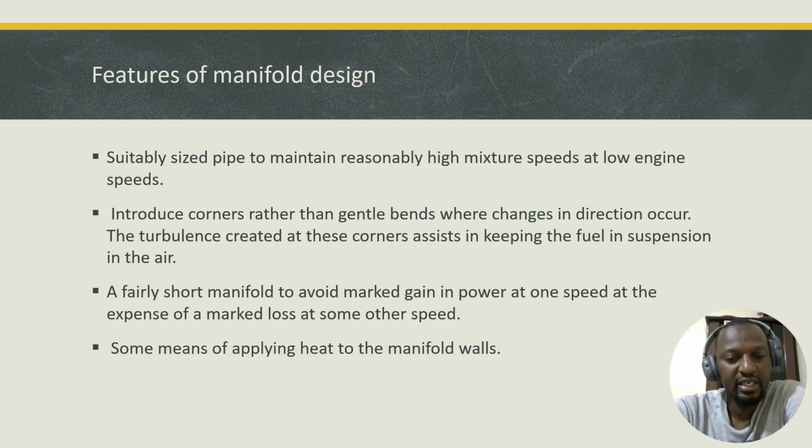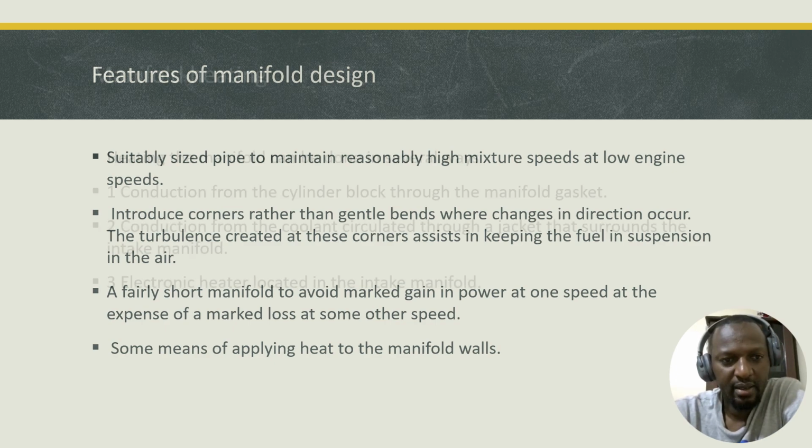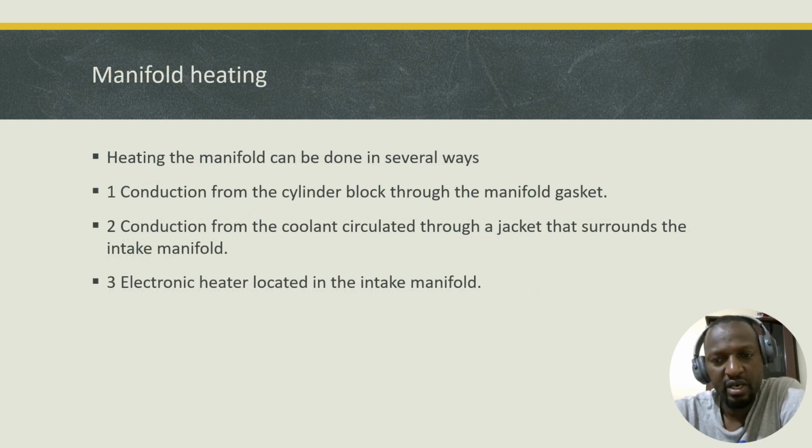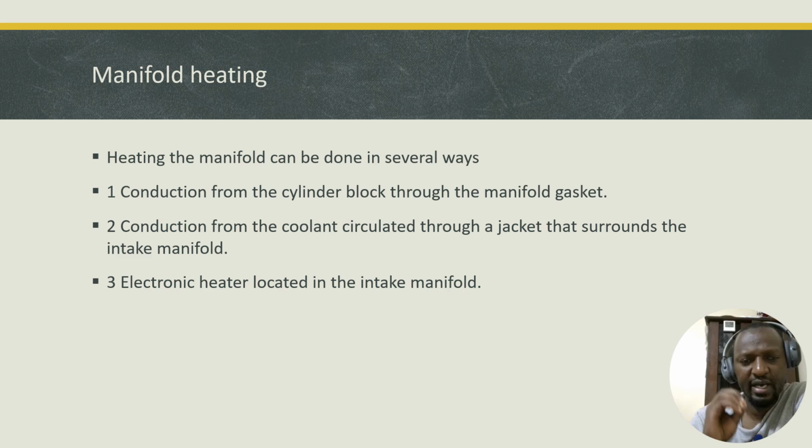And lastly, there must be some means of applying heat to the manifold walls. And we look at this, what we're calling manifold heating, because we say that we require to heat our manifolds for us to be able to achieve better atomization. Now, heating of the manifold can be done in two ways or three ways.